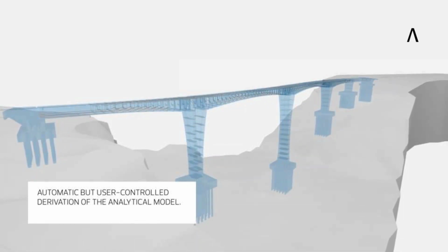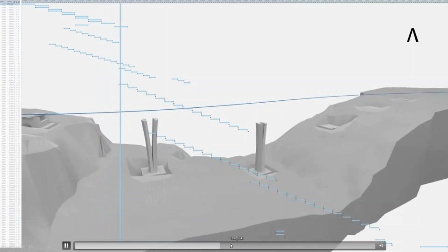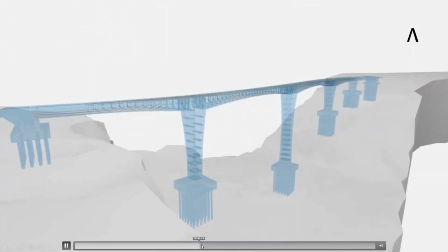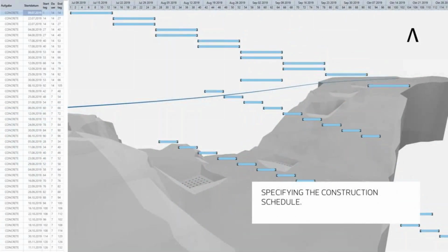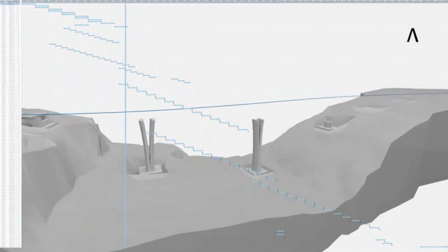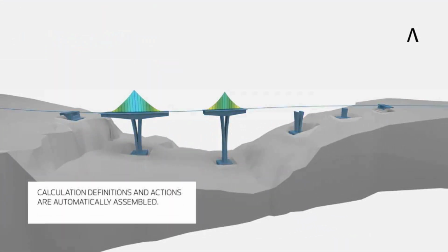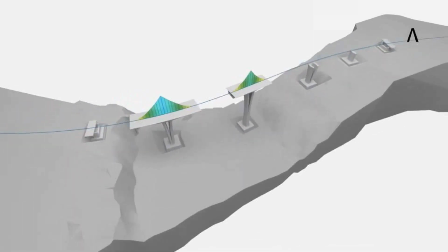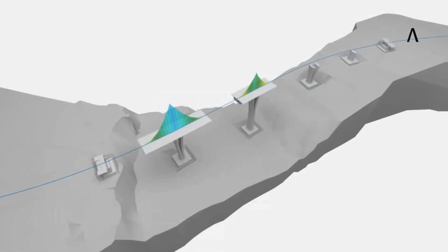So you can control the longitudinal profile of this. So it's just an interpolation that is done mathematically. But this handles also the construction stages. So based on the 3D model you did, you can make a Gantt graphic planning. So you add the component of time, which makes the BIM model 4D. So 4D is when you include the time part within the bridge.